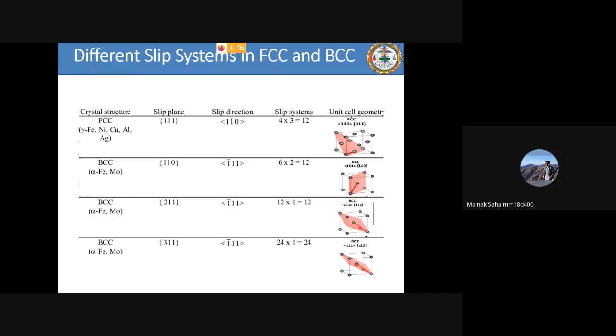But then why do you think this alpha ferrite, when I'm adding carbon to this alpha iron, to form the alpha ferrite? Why do we call alpha ferrite the softest phase in the phase diagram, right? Because if BCC is not as ductile, it should be hard. Why am I calling it the softest phase in the phase diagram?